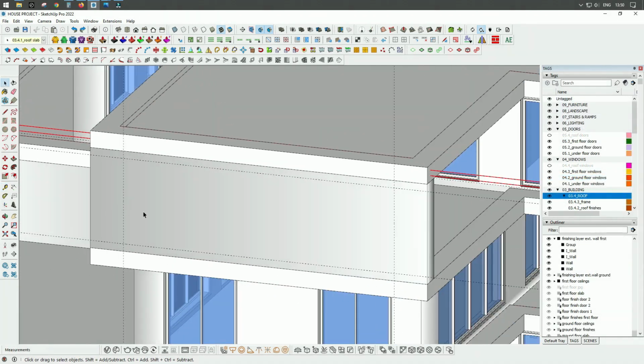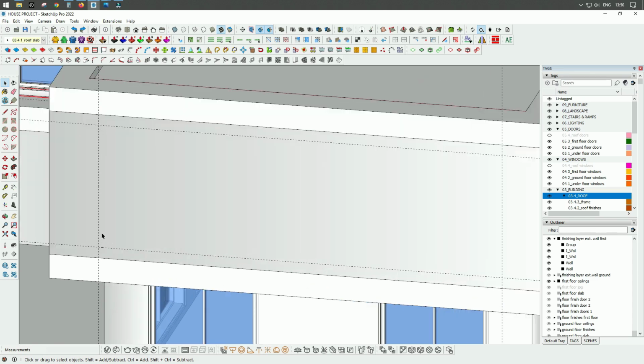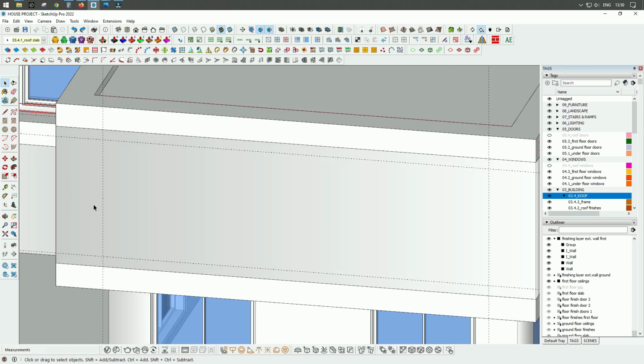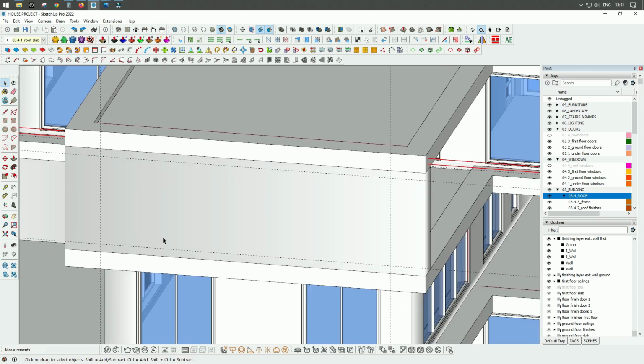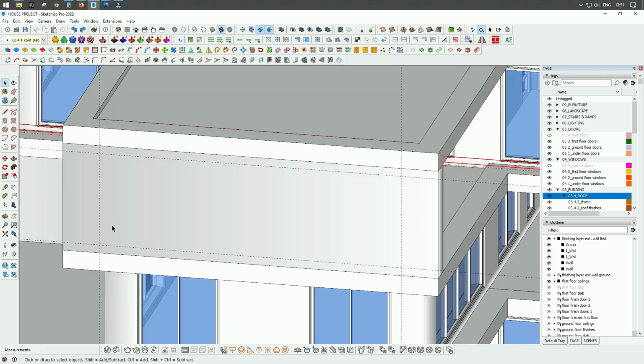So I made some calculations, and I will divide this space into 9 openings, and each opening will be 600 millimeters in width, and the distance between them will be 246.25 millimeters. So I will start draw my reference lines,